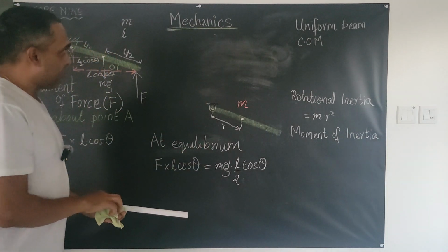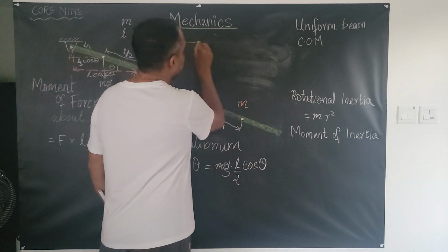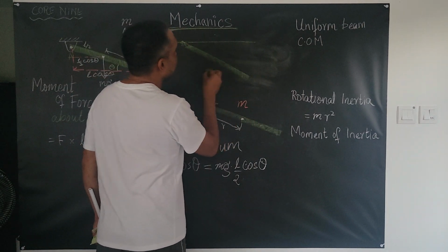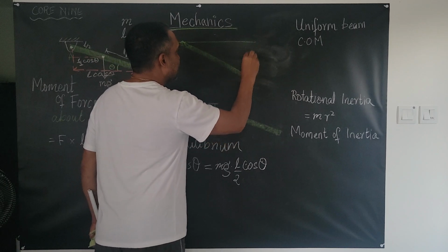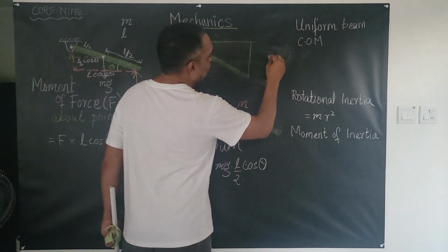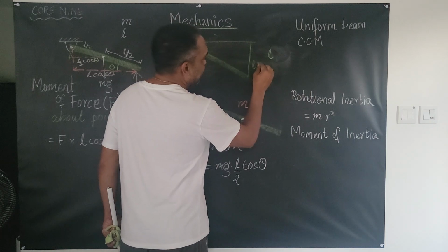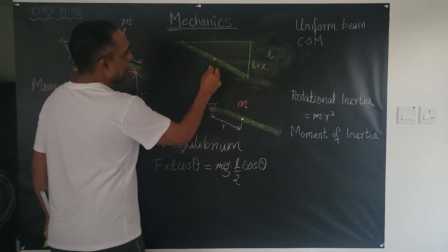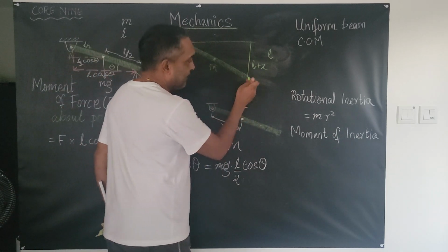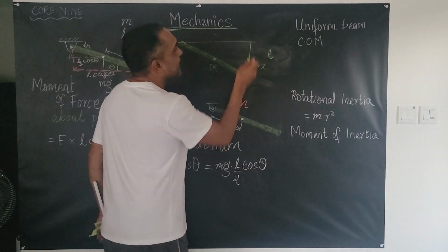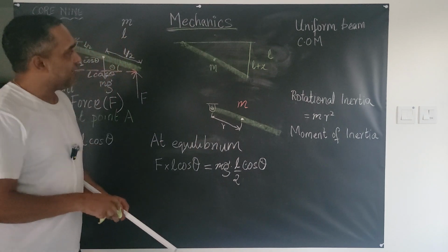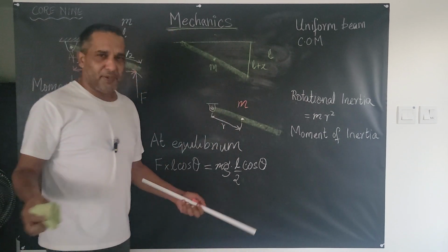If I take them out just for illustration, to show you a simple problem, and I said, hey, that's my hinge on which I have a beam, and at this end I have an elastic string, and I can't tell you, I just know its natural length is L, but now it's L plus X, and then I give you a mass, and if you know the modulus of elasticity, you can calculate the moment, equate the moment to get this force, use that as the tension on the elastic string, do your Hooke's law calculation, and solve this problem. And you can apply this in many cases.